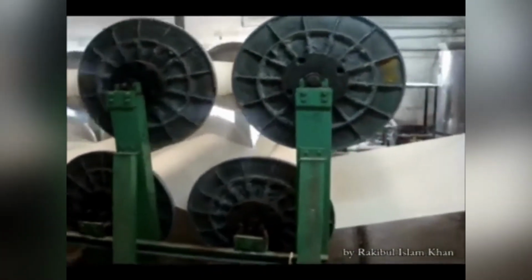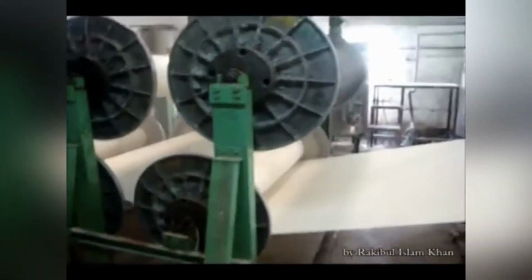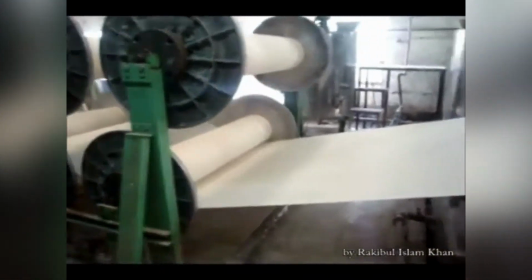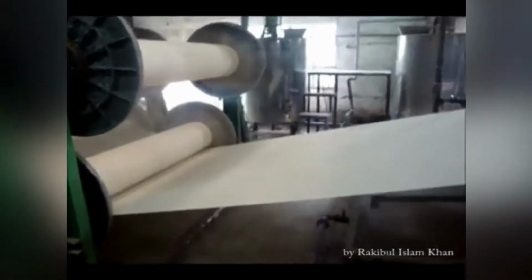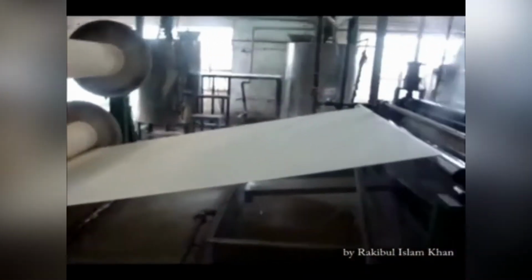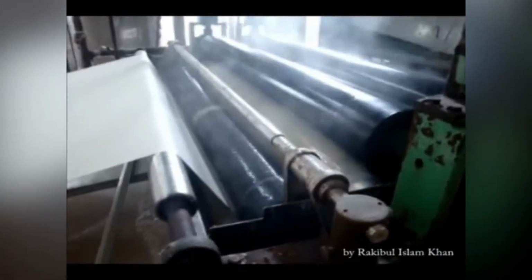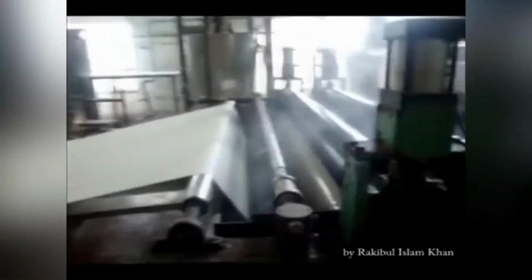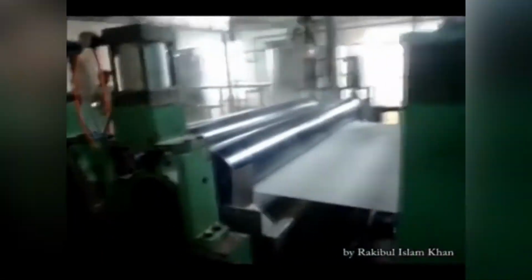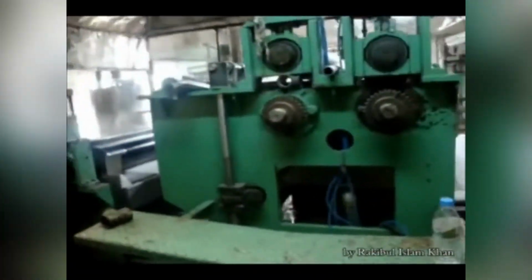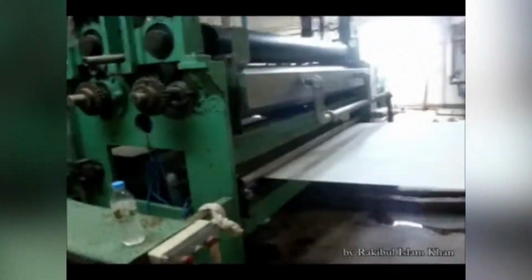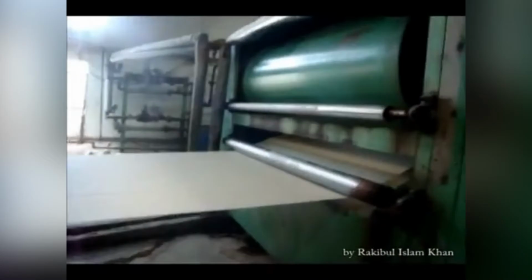Two or more warp beams are placed on the sizing machine. Yarns from each warp beam are set parallel to each other. This increases the number of warp yarn per inch. Then these yarns are passed through the sizing unit. In the sizing unit, the sizing chemicals are coated onto the yarn surface with the help of rollers and padders. After application of the sizing chemicals, the yarn is then passed through the drying unit.